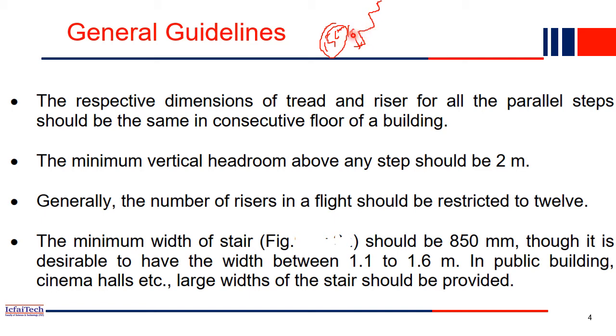Why? Because see, for example, you are visiting a big building, right? You are using the staircase. So when you are going from first floor to second floor, you are comfortable with whatever riser and thread they have provided. But from the second floor to third floor, already in our subconscious mind we have some basic idea of the dimension of riser and thread of this building. Now if you change it from second to third floor, then again it will be very uncomfortable for the customers to visit that building, right? So that's why whatever dimensions the riser uses at the ground floor, that should be the same throughout the structure.